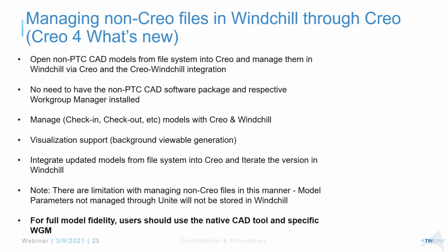I mean, we strongly encourage that you should be using that specific workgroup manager, like the SolidWorks workgroup manager, or that specific CAD system's workgroup manager. But starting Creo 4, there might be some limitations in there, obviously, but you're at least able to open the file. Let's say somebody sent you a file, you bring it into Creo, do a file open, and then during check-in from your workspace, you're able to put it back into your common space. That is possible, right? So that's starting Creo 4. PTC made that enhancement there.